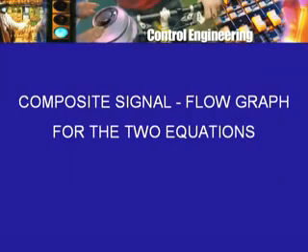I hope you have attempted the problem that I put before you to draw the complete or composite signal flow graph for our two basic equations for the speed control drive, the armature equation and the torque equation. Those are the only two equations we have. The problem was to draw the signal flow graph which will represent both these equations.